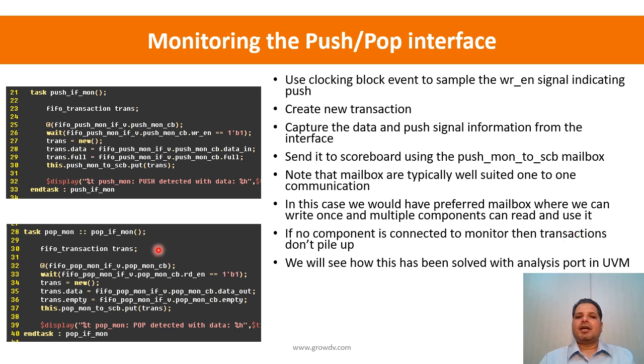and a more standardized way of building it, because here the tasks and functions that we are defining, we could define any name, right? Like main and run, I could give any name. This is a name that I have chosen, but someone else may choose different names. So when you use UVM, the same functionality gets standardized, the names of those functions get standardized, and any common code that exists gets standardized, so that everyone will do things exactly in the same way.